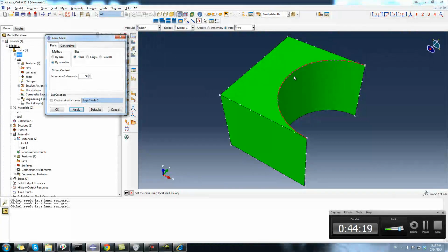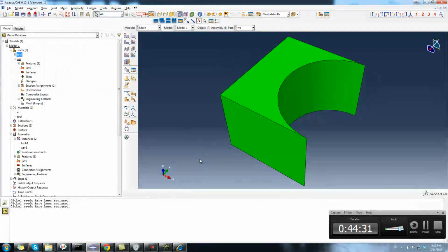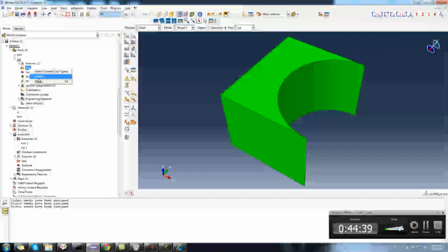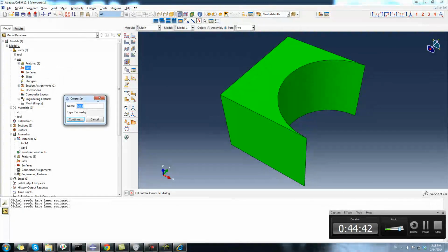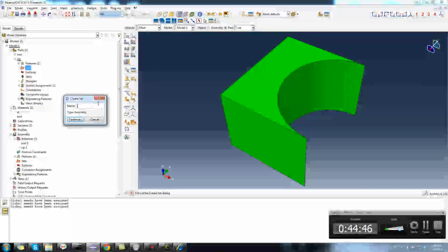Similar thing you have to do here, but you want the element number here and here to be the same. So you can select both together. How? Do you know how to define a set? No. Okay, so you can define a set. Right click. Set is very useful. Suppose this is the inside surface, so just type inside, ins.